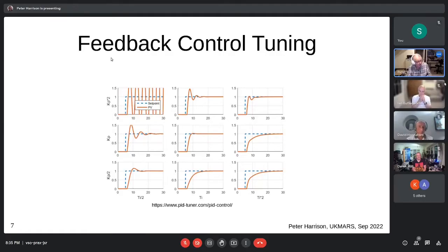There's a P for the proportional, there's an I for the integral, and there's no mention at all of how the D might make a difference, because it's using a different mathematical model to the one that you may have looked up, a statement about the maths of the control loop, and it'll talk about KP E and KD times E minus E dashed and all that sort of stuff. But here they're combined into TI.